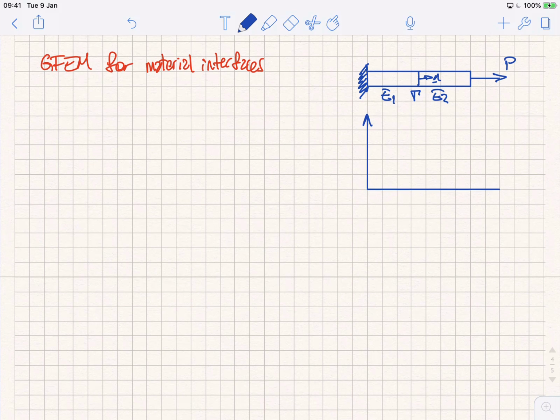which by the way is what type of polynomial? So if I have no body force there and I fix one end, so the displacement at the left end is going to be equal to 0, and then I just apply a concentrated force at the right end, my solution is what order? My exact solution? 2? Linear.